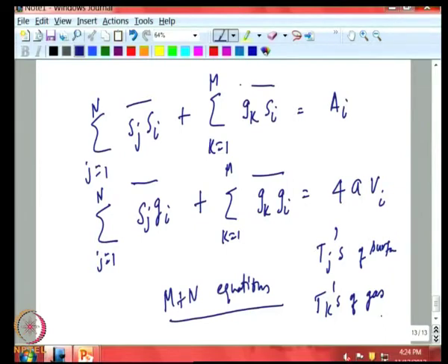So, today the accuracy of the final result is not really sensitive to how you do the computation, but much more sensitive to how you calculate the properties. So, the emissivity of the gas, the emissivity of the surface, those are the inputs in which there is a large error. As indicated earlier, emissivity of surfaces is not that easily available, and it depends on the surface condition and the history. So, those numbers have a certain amount of inaccuracy unless you know the state of the surface accurately.